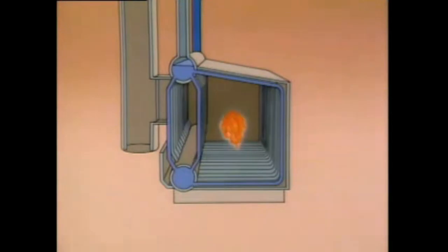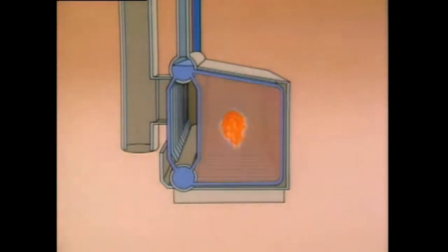As fuel is burned in the combustion area, heat is transferred to the adjacent water tubes. The combustion gases then flow out of the boiler. Water circulates from the upper drum through the water tubes and into the lower drum. The lower drum is often referred to as the mud drum.